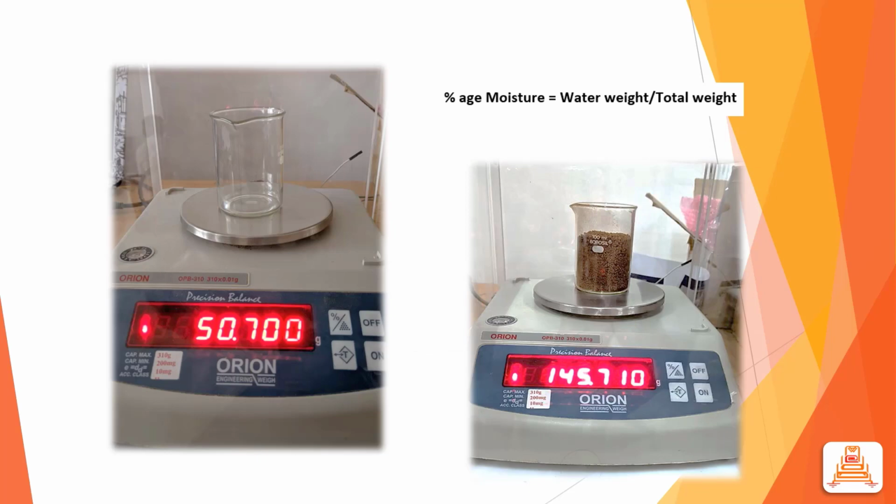The following procedure is followed in order to calculate the percentage moisture. Initially, the soil is heated in order to obtain the dry soil by removing the moisture content. A beaker is filled with known weight of dry soil. Moisture sensor is immersed. The voltage is noted. The moisture sensor is removed. Then 5 ml of water is added and is mixed for uniform distribution, and corresponding voltage is noted by immersing the moisture sensors. These steps are repeated till the moisture becomes saturated.